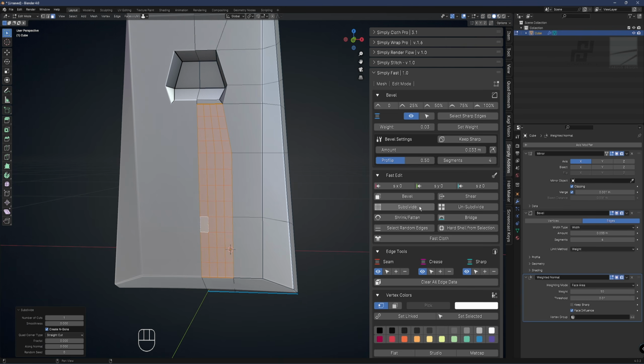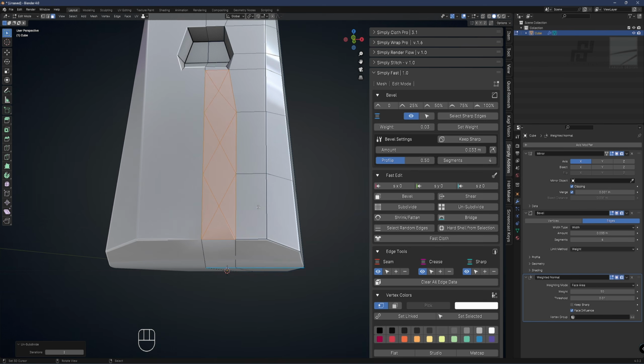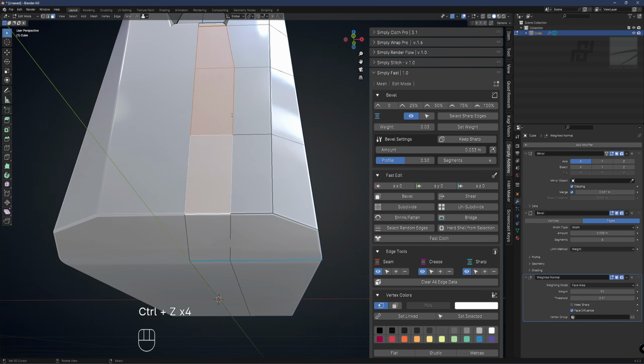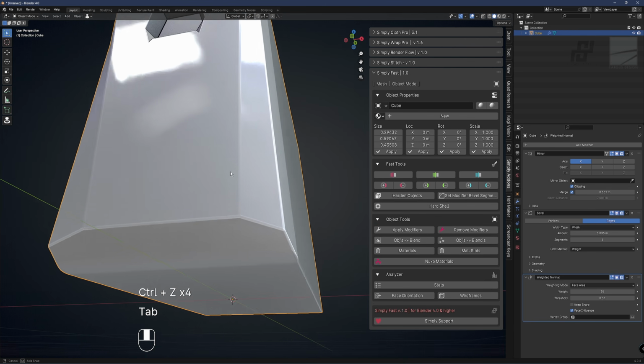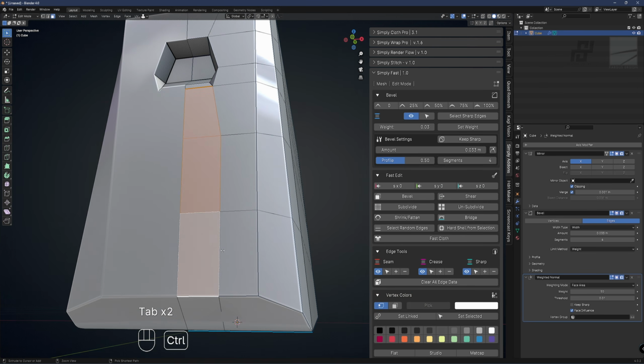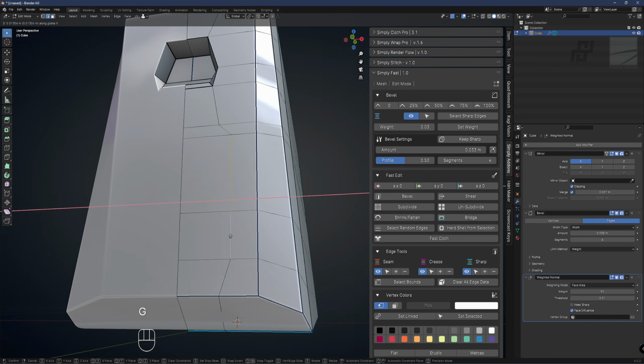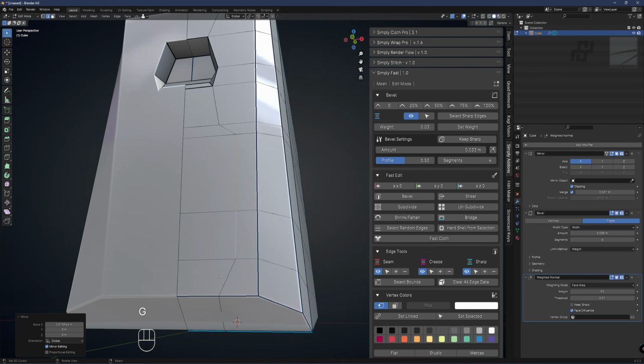So I just hit some bevels here or unsubdivide, and we see, oh man, the shading is breaking down. This is because of this topology. So we need to be sure what we're doing, of course. So if I'm happy with this main result, I can here start to create something like this.